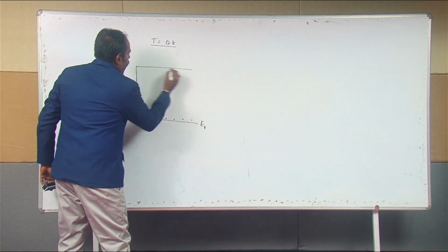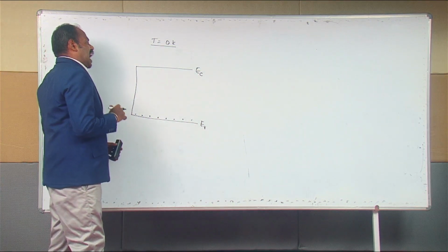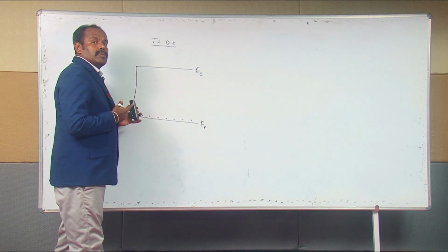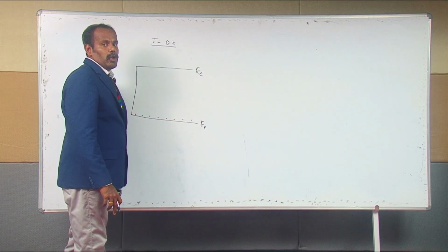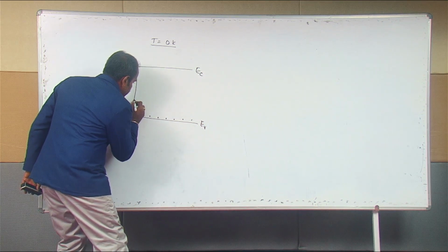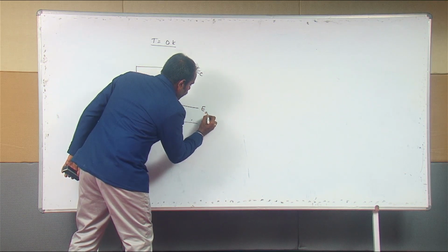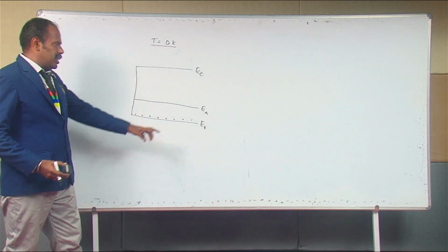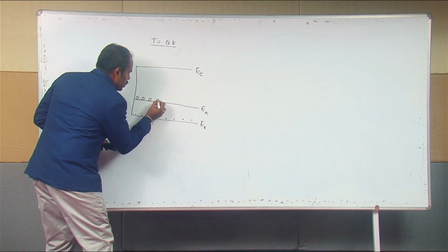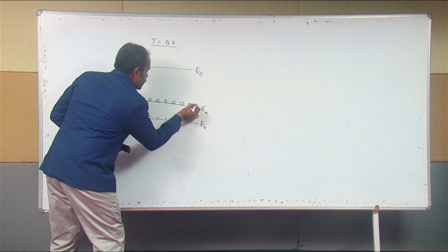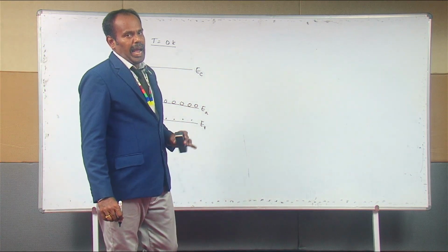And you also have the conduction band, which is ready for electron occupancy. As you introduce the boron atom into the system, what is newly introduced? Acceptor sites are newly introduced, and those acceptor sites, or in other words those holes, will be residing at a new energy level called the acceptor energy level, that we refer to as EA. These circles are representing the acceptor sites which are introduced by the addition of the trivalent boron atoms.